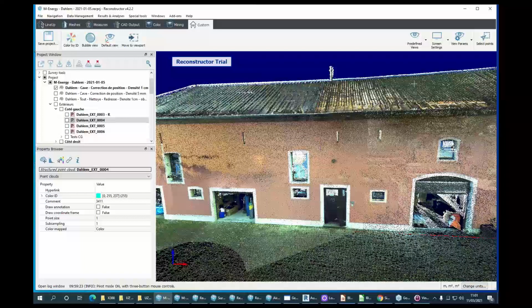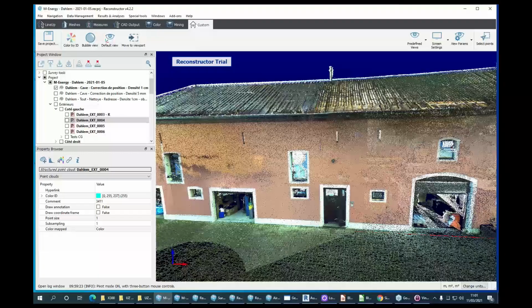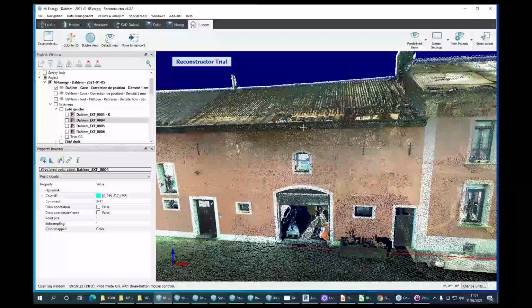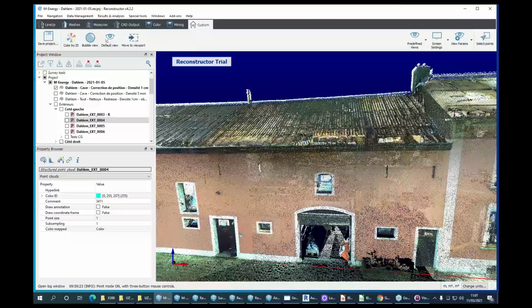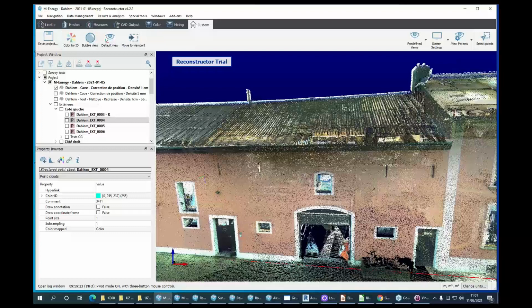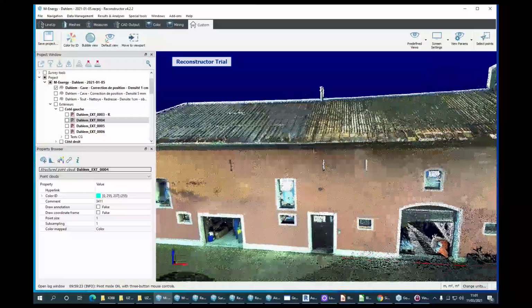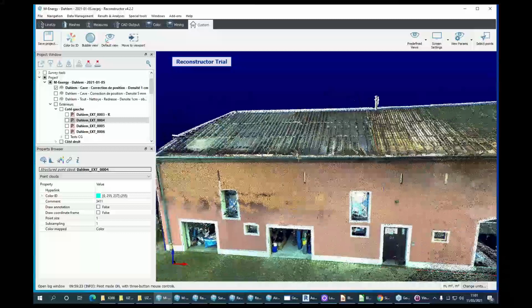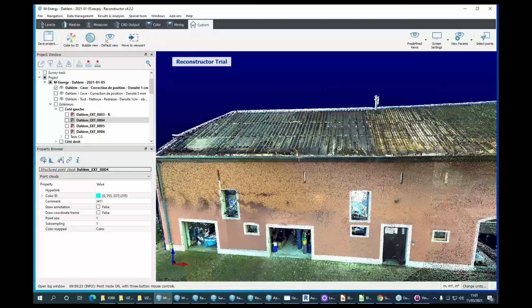We know that there could be a small geometric discrepancy. It can be up to 2 or 3 millimeters, rarely more than that. On this one, if we look at the wall thickness, it really matches with what we saw on site. Everything seems to align, so I think we are actually very, very good, more than we usually plan for. But I always say that it is not going to be completely perfect. You have to plan when you do the scan to have the inside and the outside in some of the pictures so we can do the alignment.